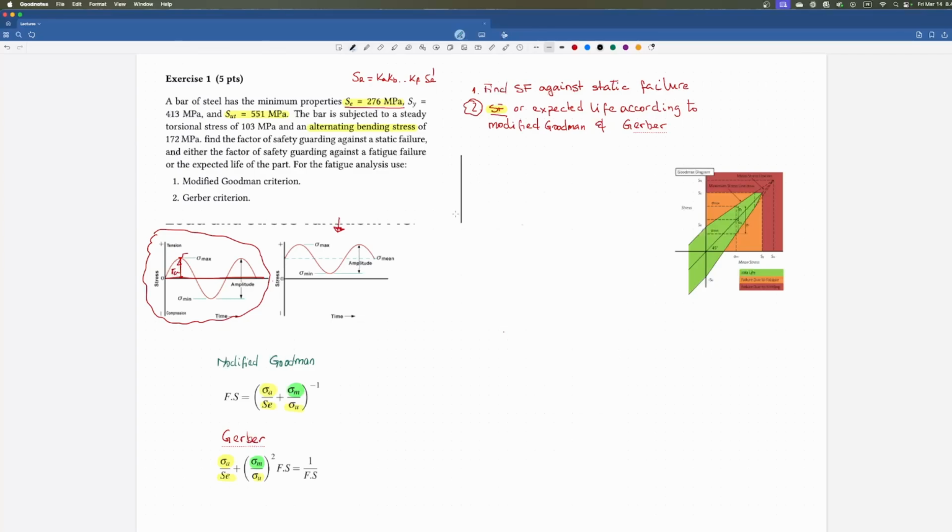So remember that we have this stress life curve, this S-N diagram, which was something like this. It went down, and then it came down again, and then it went like this. And this part here was what we know as the endurance limit. And then here on the top, we remember that this part was the ultimate strength value.